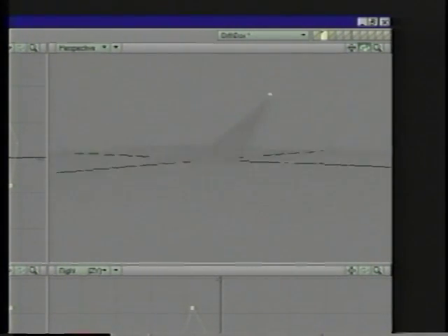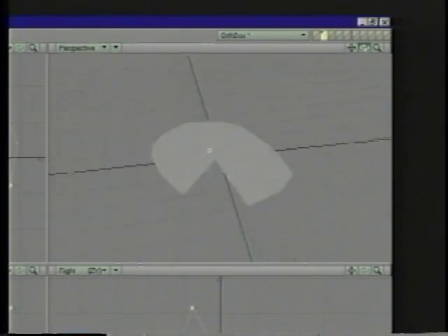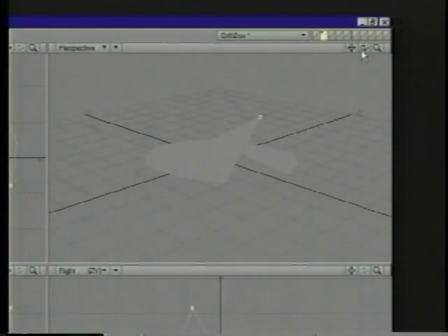And that's because we have what's called a non-planar polygon. And that means that all of the points that make up the polygon do not lie in the same plane. Now, you can get non-planars on anything with more than 3 points. Obviously, if you have 3 points of a triangle, those points are always going to lie in the same plane. You can't get them out of the same plane. But if you have 4 points, one or more of those points could be out of the plane of the other points, and you're going to get these problems.